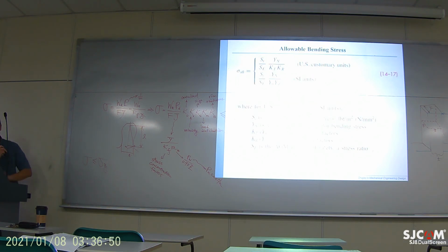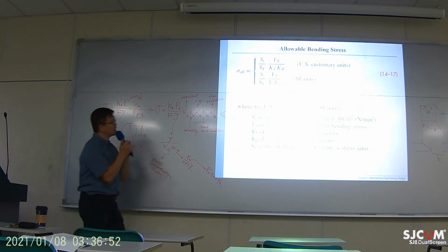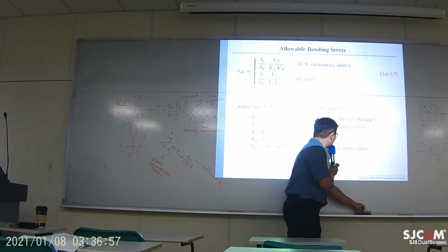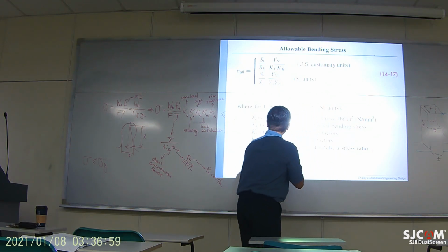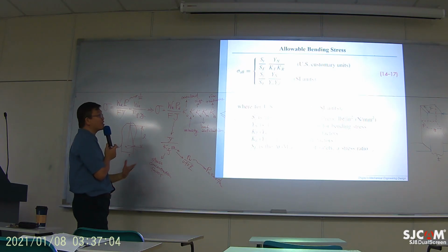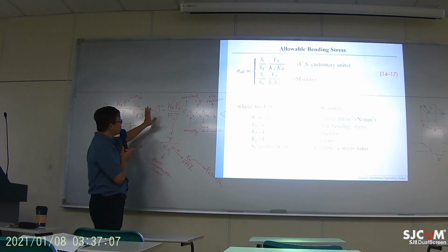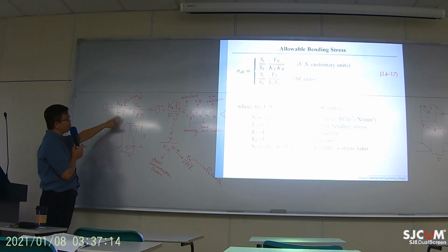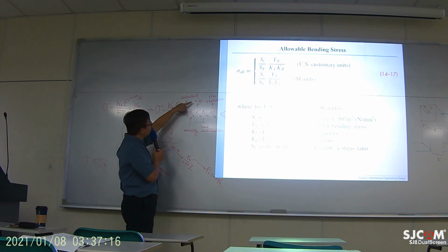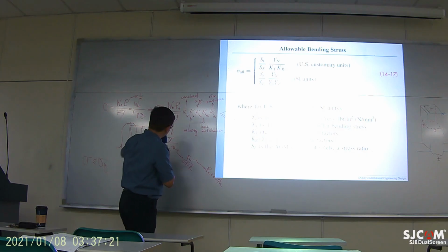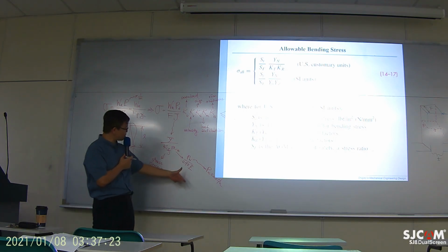Here, ST is the allowable bending stress. So basically, you can use your yield strength for ST. So you estimate your stress in a certain way. However, it varies depending on very different conditions. You have overload, size, ring thickness, velocity, load distribution. You correct them. You also have stress concentration factors.